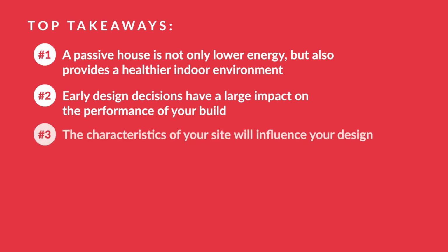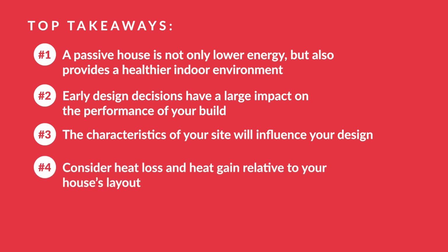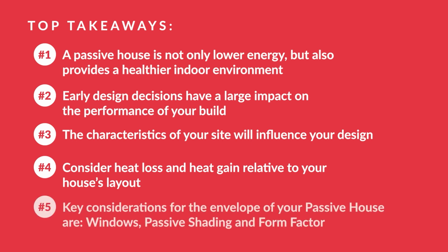The characteristics of your site will also have an influence on your proposed design solution. Consider laying out your home by thinking about heat loss and heat gain relative to those wider site characteristics. And key considerations for your envelope are windows, passive shading, and form factor.